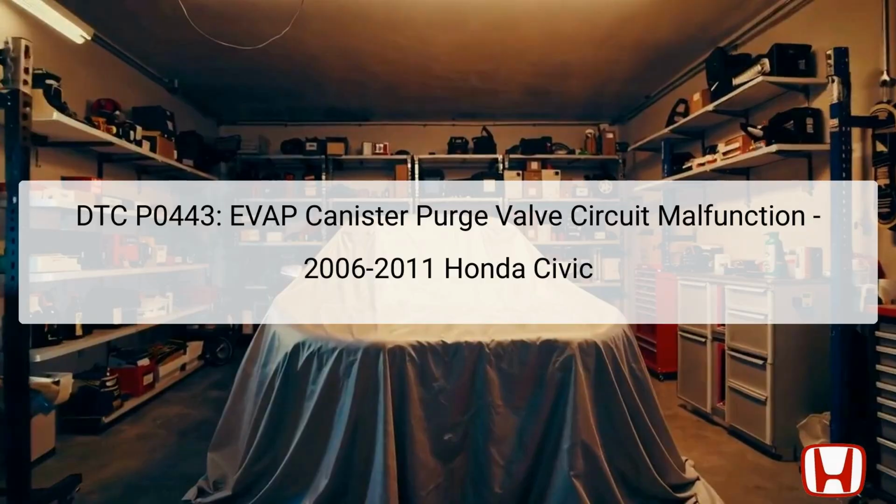The error code P0443 indicates a malfunction in the EVAP Canister Purge valve circuit of the 2006 to 2011 Honda Civic. The EVAP (Evaporative Emission Control) System recycles gasoline vapors from the fuel tank to prevent them from escaping into the atmosphere. The purge valve, located in the engine compartment, is responsible for controlling the flow of fuel vapors back into the engine for combustion. A malfunction can lead to increased emissions and affect the car's performance.